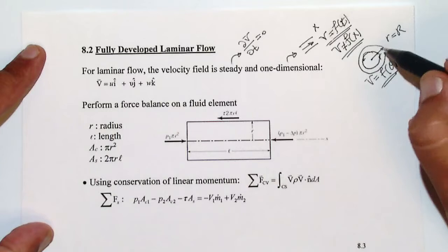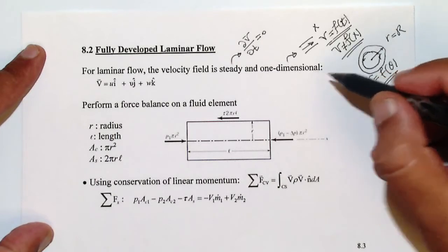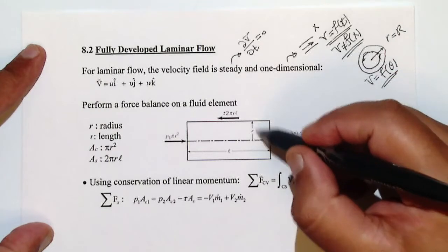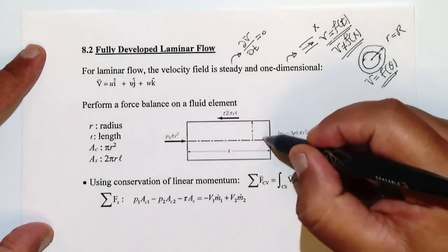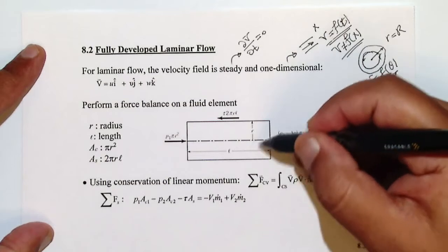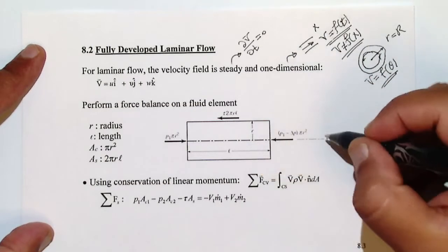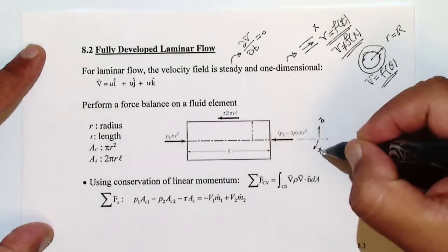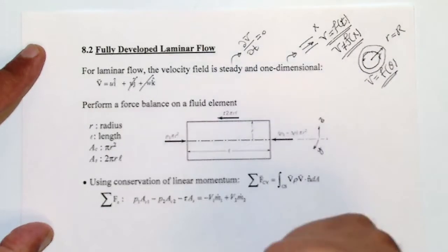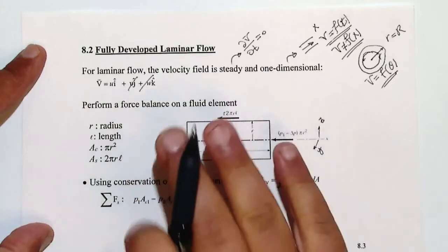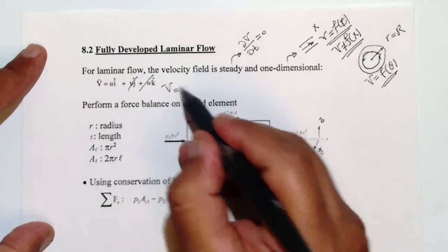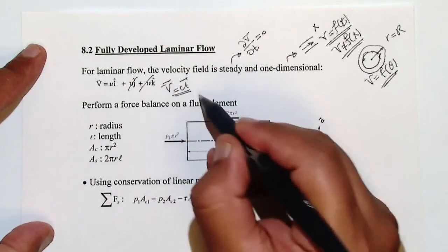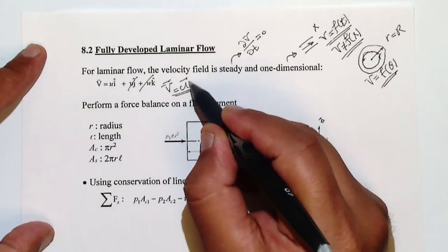And also when the flow is one-dimensional, it means that you have only one component of velocity. Which component? It's not going to be v. If that's your x, the flow is not moving upward, it's not moving in y, and in z and y they're not moving, so both of them are going to be 0, right? So velocity is only the u component, right? Velocity is u in the i direction.